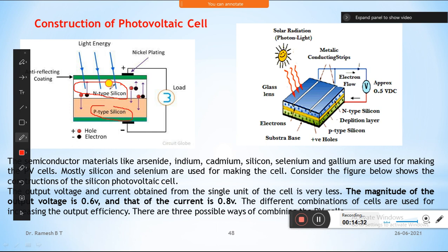So here we are adding phosphorus or arsenic, and here we are adding boron. So for the same silicon, if you add these 2 different types of materials, it will become n type and p type. N type means it's a negative type, meaning 1 excess electron. P type means there is a deficiency of electrons. Clear? And this deficiency is expressed in terms of excess holes that are free to move on the lattice. Deficiency means it creates the hole.